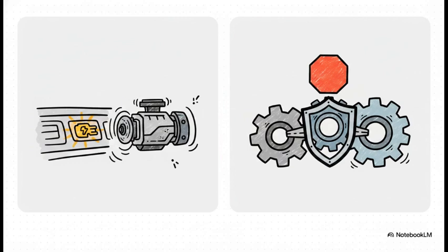And it communicates these problems in 3 main ways. First up, we've got alarms, or warnings. Think of this exactly like your car's check engine light. The motor keeps spinning, production is running, but you definitely need to investigate. Second, we have faults, which we commonly call trips. Now, this is like your car's engine deliberately stalling out to prevent a catastrophic blowout. The drive actually cuts power to protect your equipment. And finally, third, we have configuration errors. This just means the drive has been programmed with conflicting parameters and literally cannot start until the math is fixed.